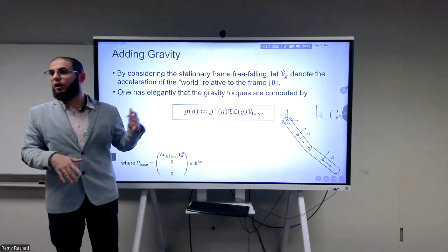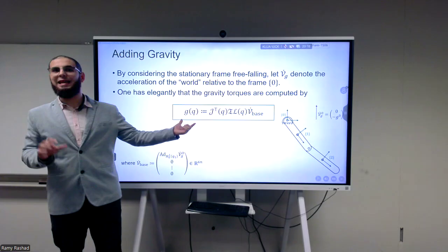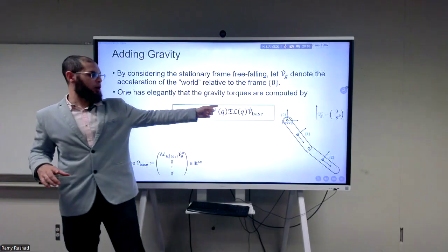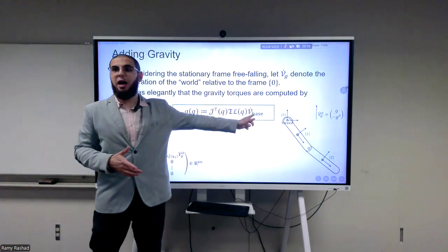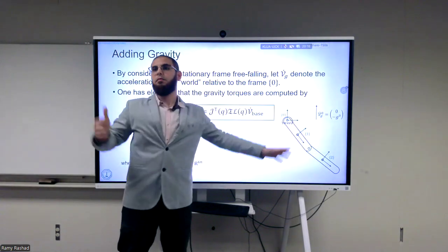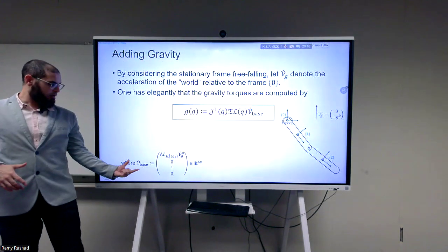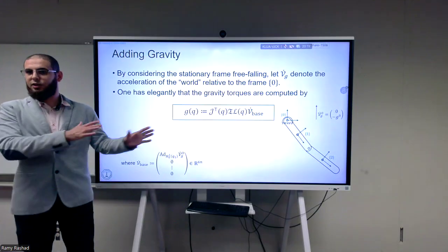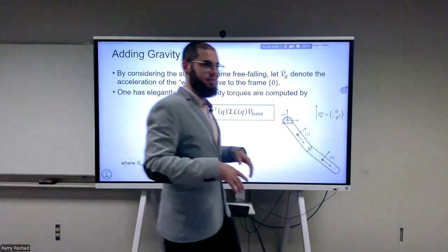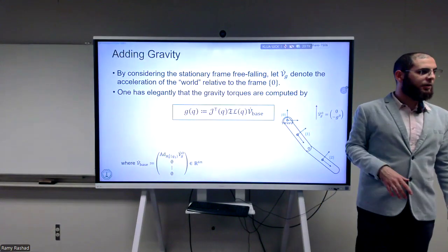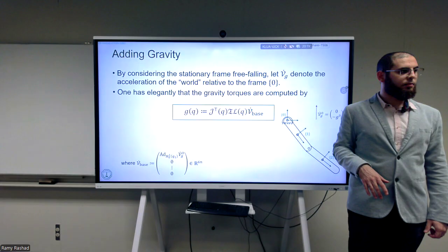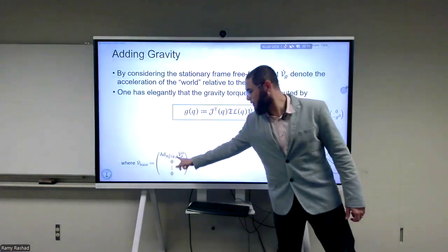So the bottom line, of course, I'll not go into details here, but the G of q we can very elegantly write as an equation like this. Assuming it's J transpose multiplied by all of the inertia multiplied by the L we calculated, multiplied by a v dot of the base. We assume that the base of the robot is just accelerating up. And this v dot of base will have something that looks like this. This is only for your eyes to see, or just implement it in the code and see where it works. You really need some time to look at this. Then we have to include this component only for the base? We don't have to include it for the others? Absolutely, yes. You have to only include the v dot for all of these terms.